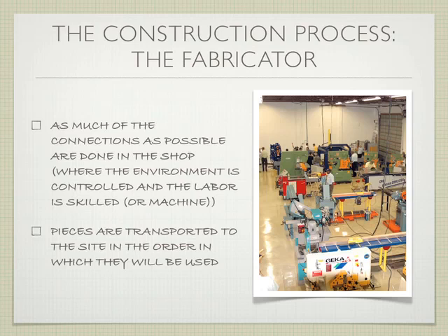Think like railroad car type thing. So they were making these vessels, right? They're making it by rolling a certain section of steel into a cylinder and then welding it together, right? And then capping the two ends and welding those together. As much of this particular vessel as possible, they would have computer-driven welding equipment actually make the weld, because this needed to be such a high precision weld.